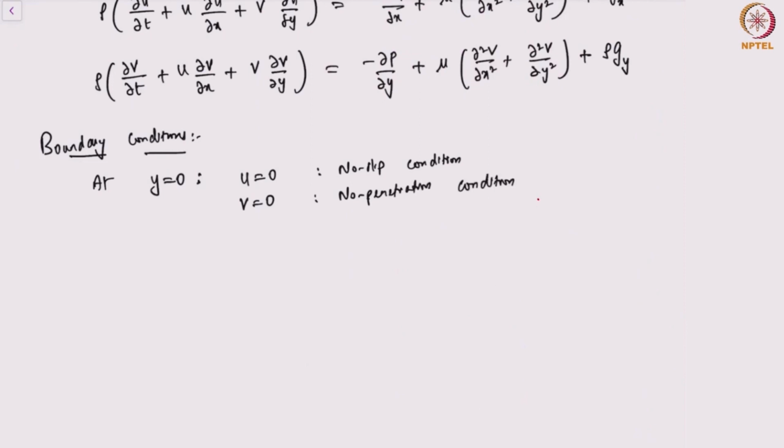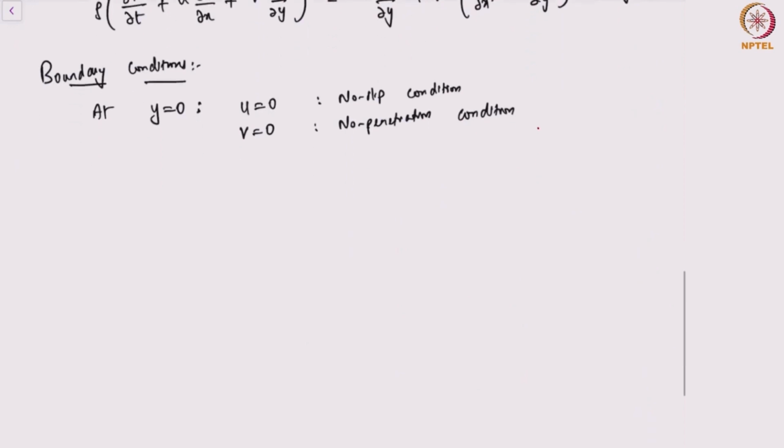These are common boundary conditions that you would expect at solid surfaces, but these are not, of course, the only boundary conditions. You can have slip at a wall. So u equal to 0 is not satisfied in such systems. If it's a porous wall, you can even have fluid entering from the bottom. So therefore, v equal to 0 also would not be valid, but we will ignore those special cases for now. The focus is primarily on the interface conditions. Now let's look at the interface conditions.